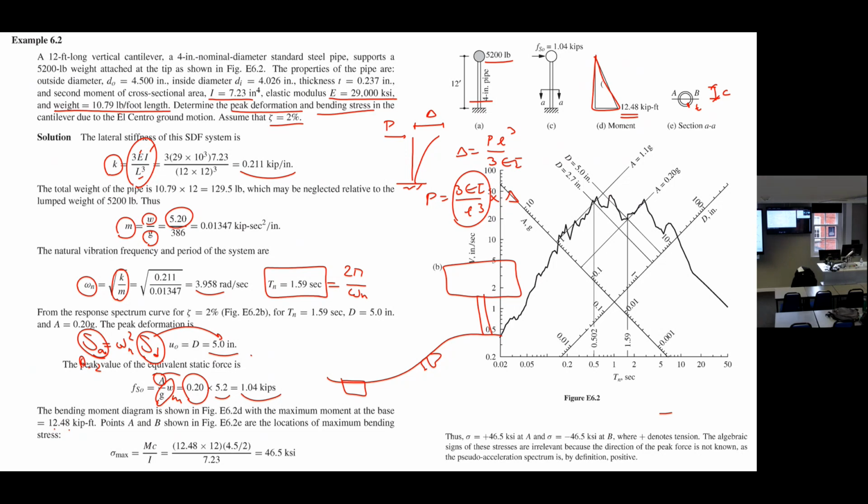The allowable stress, Fy for the steel, is 235. It's more than Fy, which means this is not safe. The section is a hollow steel section, and the height is 12 feet. The question is what we should do as structural design engineers to solve the problem, since the resulting bending stress is more than Fy.